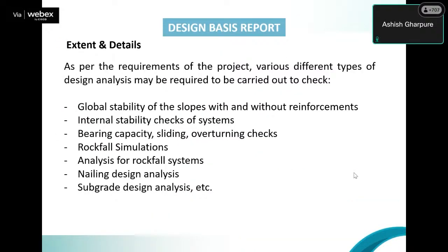Now we prepare a design basis report. Depending on the site situation, you need global stability checks and internal stability checks of the systems you have provided. If it's a wall, then bearing capacity, sliding, and overturning checks. If it is a rockfall situation, then rockfall simulations, analysis for the rockfall system, nailing design, subgrade design, and so on. Right. Next, please.